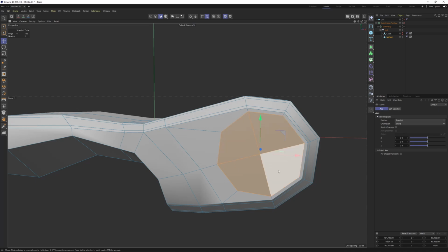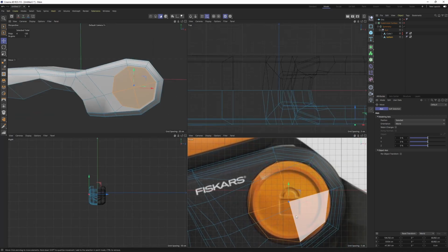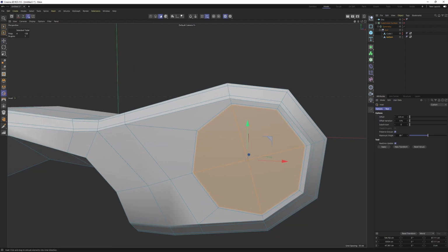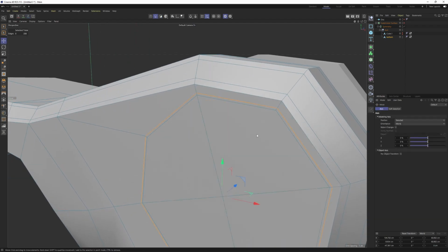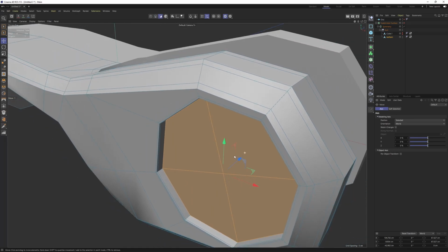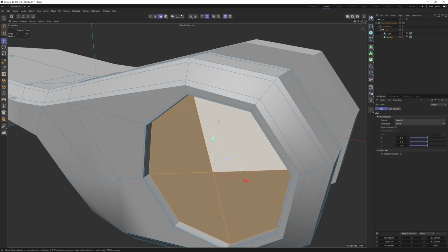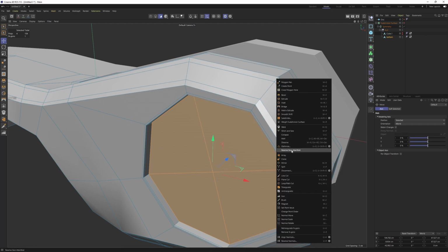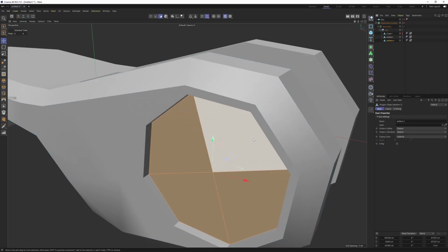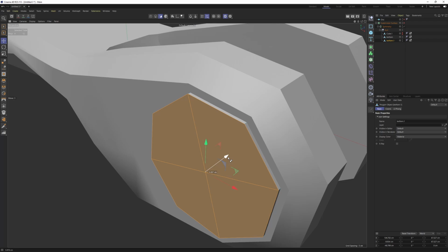Now let's check here on that disk shape. I will make another inset. So this is going to act like supporting edges. And press Ctrl slightly one more time. These are going to act like supporting edges. After that point, I can split this, or it should be somewhere here. Yes, split. Go back to the original one, delete, select that one. I'll press Ctrl, extrude. Let's see, I need another inset.